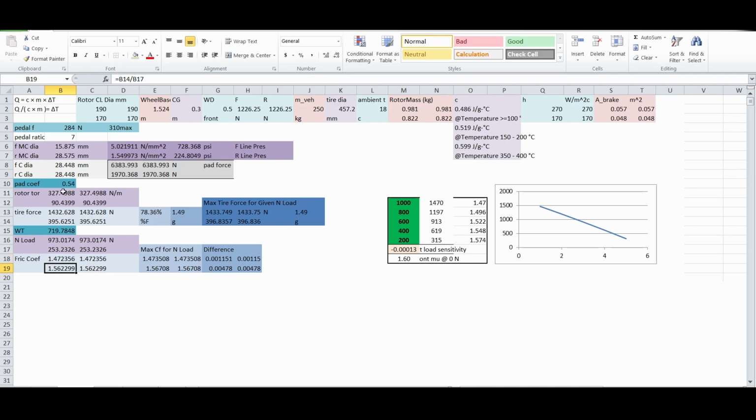Just all of this here is what we calculated before. We're just adding in coefficient of friction using our tire model, what's fit to the curve for coefficient of friction and normal load. We could subtract those, and then we can see how close we are to getting them to lock up. Where you see the rear still has a little bit more to give than the front.